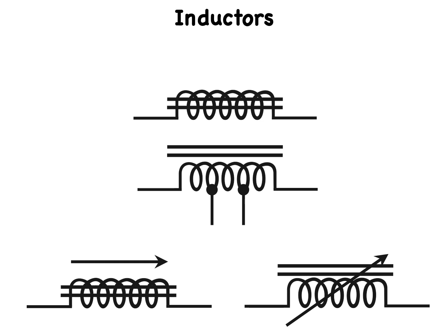At higher frequencies, solid iron and laminated iron cores aren't efficient enough to function in inductors. Engineers would say that they have too much loss. At frequencies above a few kilohertz, a special core is needed if you want to increase the inductance over what you can get with non-ferromagnetic core materials, such as air, plastic, ceramic, or wood. The most common substance for this purpose consists of iron material that has been shattered into myriad tiny fragments, each of which has a layer of insulation applied to it.